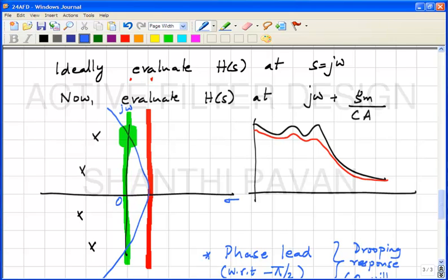And intuitively this makes sense because if you had parasitic pole which causes excess phase, the quality factor goes up, right? If you want to bring the quality factor down, what must you do? You must increase the damping, which is equivalent to putting resistors everywhere, right, in parallel with the capacitors, so that the quality factor comes down.